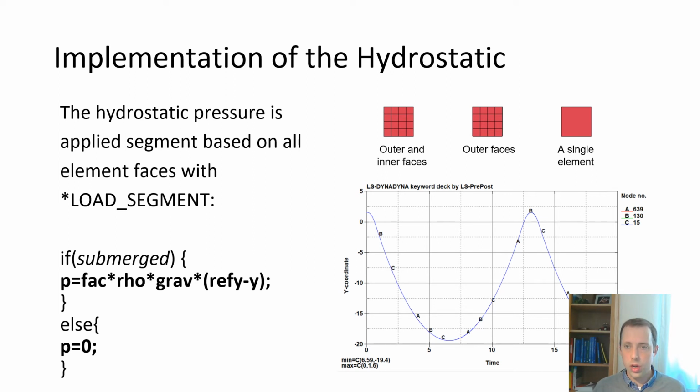We implemented also hydrostatic forces. For that, we used a segment-based approach, where we add to all segments, also the internal faces, a pressure which was computed according to a simple equation. That means that we have a pressure dependent on the y-coordinate for the submerged elements, or otherwise, if the element is beyond the water free surface, we set the pressure equal to 0.